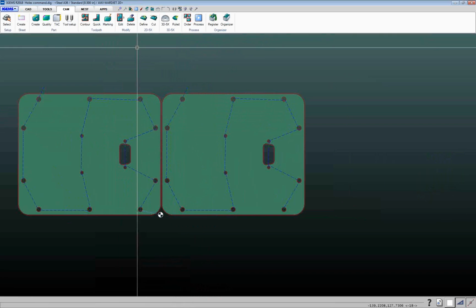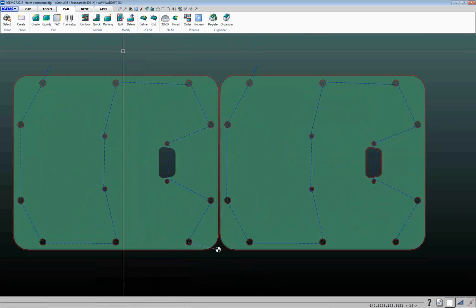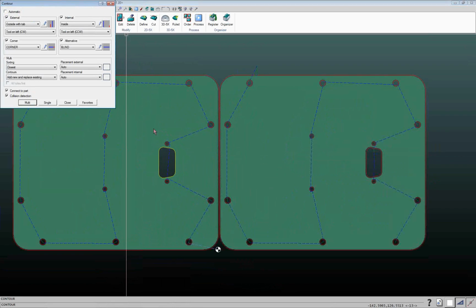Sometimes you might get a situation where maybe for whatever reason we don't want to cut a geometry. So I don't want to actually WaterJet cut that for whatever reason. But then I decide I want to change some of my lead-ins. So I've gone through, I've set my toolpath how I want it, but I don't want it to add a lead into this cut in when I add my leads again. And that's where this choice of replace existing can come in handy.